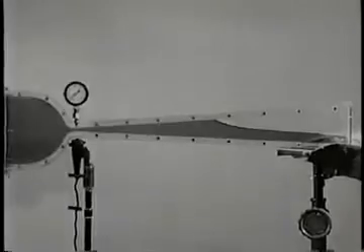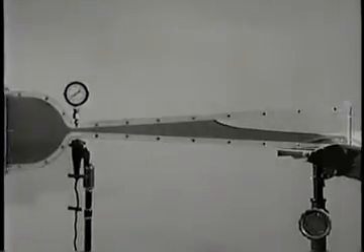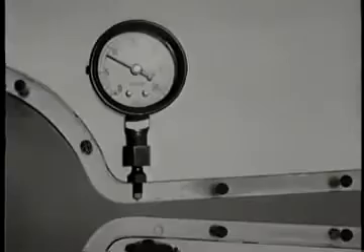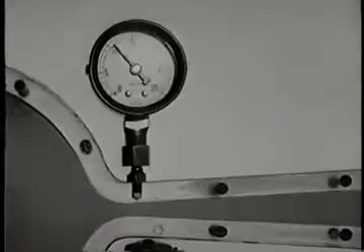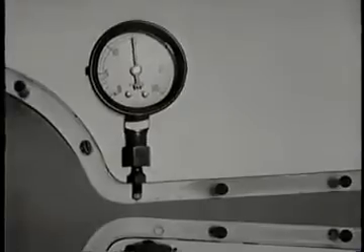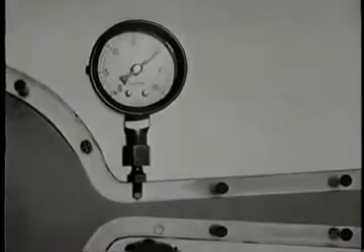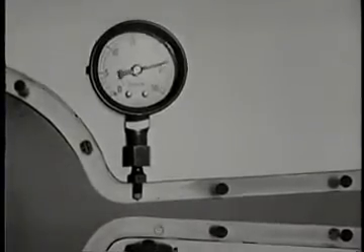In this experiment, water flows through a venturi that discharges to atmosphere. As we increase the flow, all pressure differences increase with the square of the velocity, and the pressure at the throat decreases. The gauge shows vacuum, and the pressure at the throat is now about 20 inches of mercury below atmospheric. Watch the throat. These patches that form are actually steam. This is cavitation.